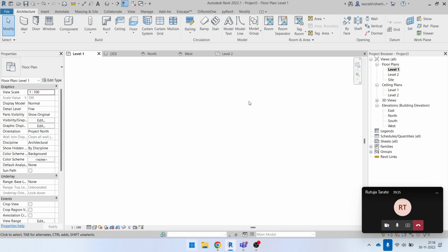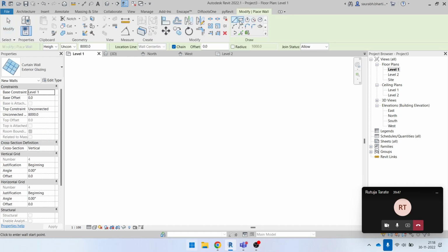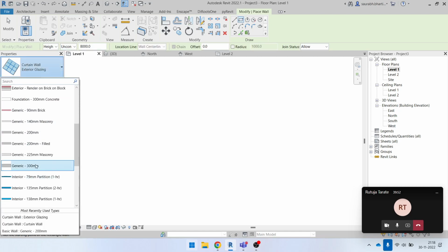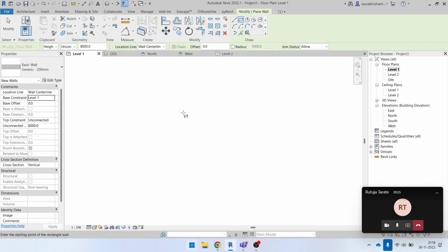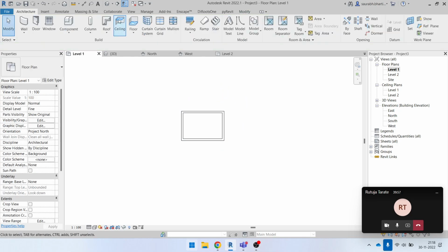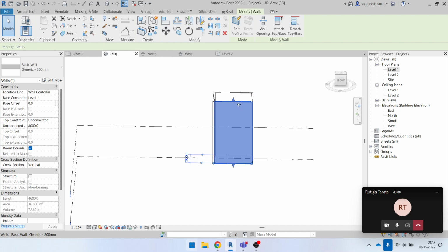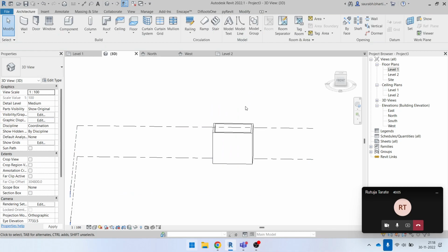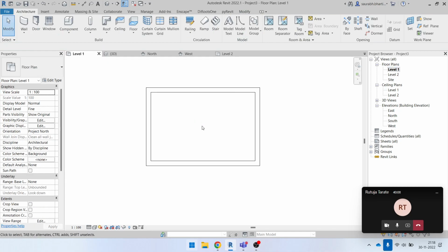The perpendicular walls, on the side where we took the curve, the walls on that side. If you want to cut that, okay, then just show me your screen. Let me show you how you can make a cut. Like I told you on the first day, this is how you can do it. I'm just taking a wall here. So in some case we just want this wall to the level 2, and let's assume that there's a ceiling here, like this.